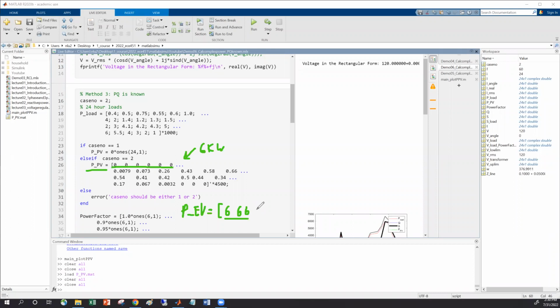Suppose you charge 3 hours, then it is full, and then you can put 0, 0, 0 here. Then you can see, if you have an EV at your home and you only charge it at 1 to 3 a.m., what the voltage drop would be and how the load profile would change. By using this code, you can simulate a residential household.